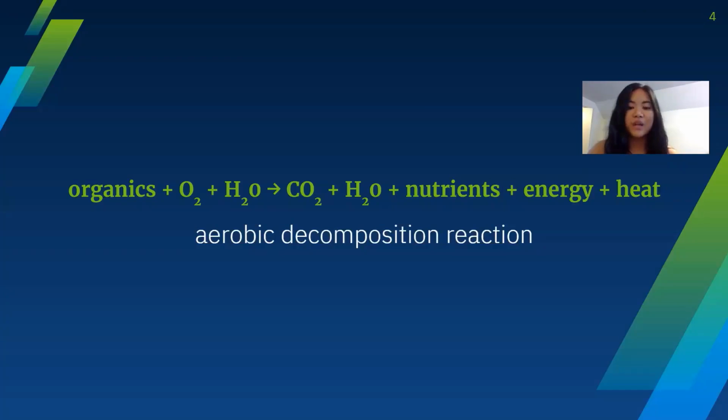The main reaction that drives the activated sludge process is the decomposition of organic matter. Decomposition happens when microorganisms, such as bacteria, break down dead plants and animals to obtain energy. Bacteria can use available organic material to grow, reproduce, and convert them to end products. Bacteria are able to metabolize quicker in the presence of oxygen and heat. In order to obtain the desired level of performance in an activated sludge system, a proper balance must be maintained between the amount of food and the amount of organisms.